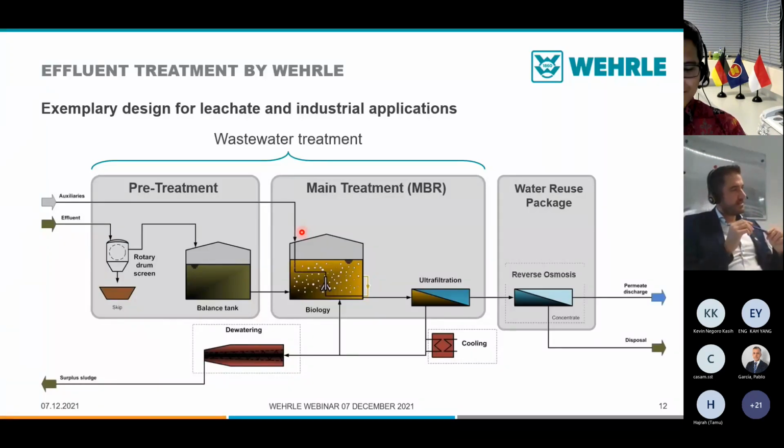Here we have the schematic drawing, a bit more like in a 2D scenario. We see here the jet ejector. On one side of the ejector, we are pumping the sludge in a circular way out of the tank and pumping it into the ejector. From the top, we pump air inside. So the air and the bacteria get mixed in the jet ejector and get spread out in the tank.